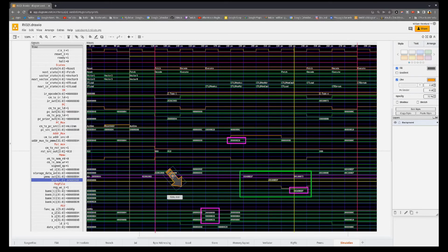The next thing to look at is we are loading the destination register based on the offset plus the RS1 register. And so our ALU is being set up with the X0 being our base and the immediate value being added to it. And there you have it. Right there is the address of where the data is located.